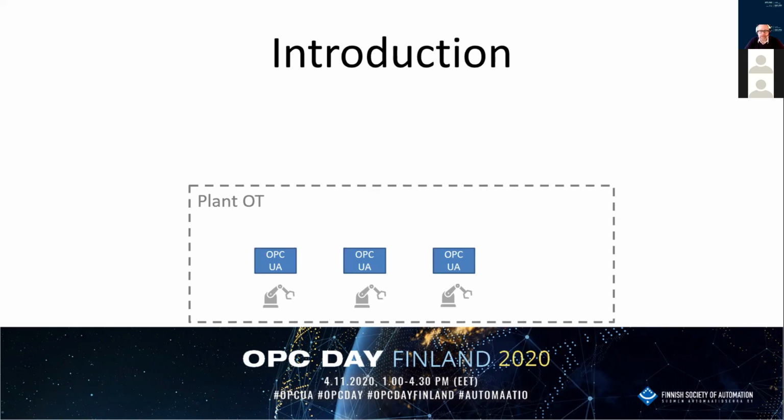So basically, if everything is good, there is physical equipment locally in many places on the site. They have their OPC UA server, hopefully. It could of course be legacy, so we need to convert that to OPC UA with different tools. But basically, they have all the information about the physical equipment. That information is used by different applications, like normal SCADA and MES solutions.